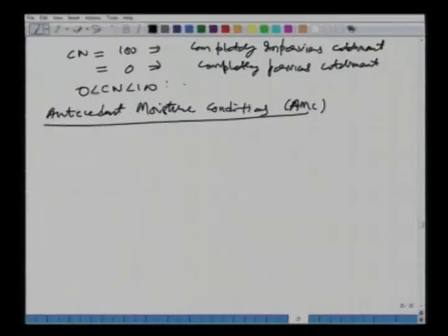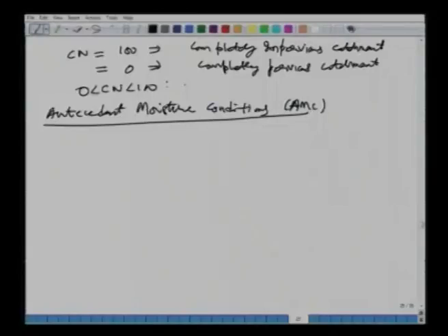Once you have done that, then you look at the catchment conditions, whether it is residential, whether it is rural, whether it is paved areas or different kinds. Within rural and within urban areas, there are various categories. Depending upon these 2 parameters, the curve numbers have been specified. And in the book there is a table which specifies the curve number as a function of these 2 things, which are the soil type and the land use, land cover conditions. In short, that is what I am writing.